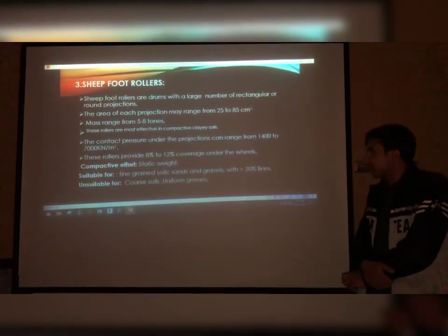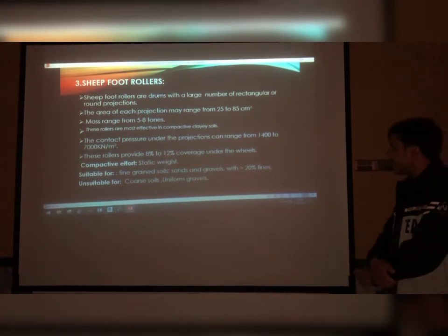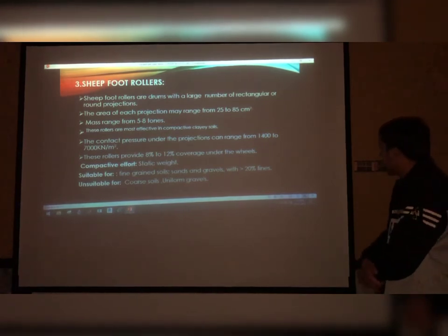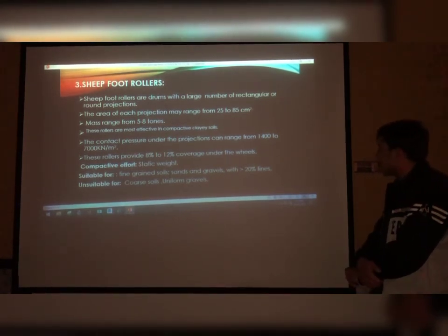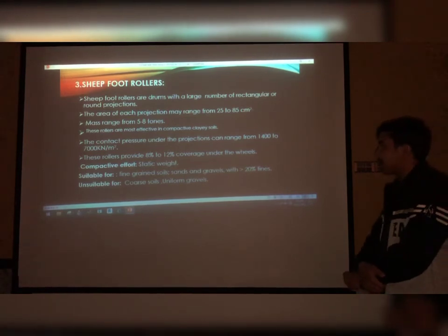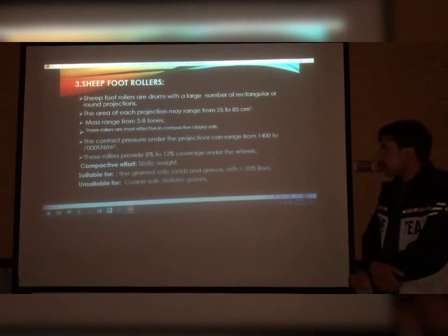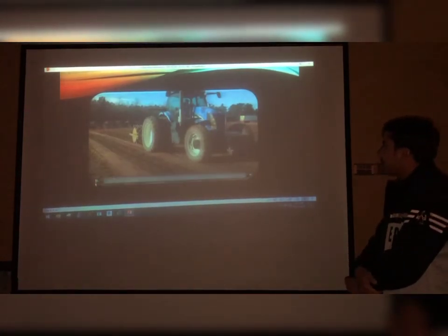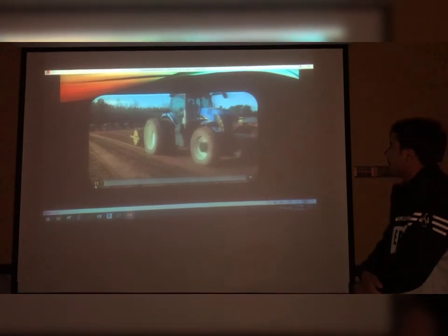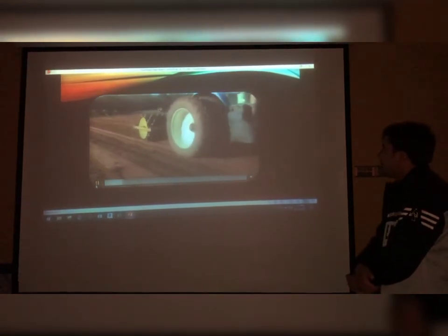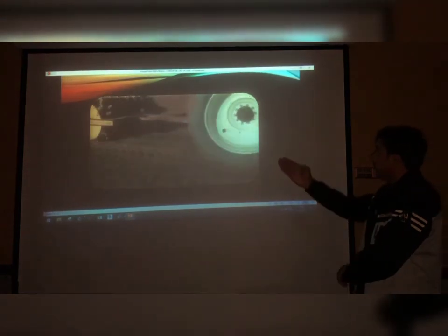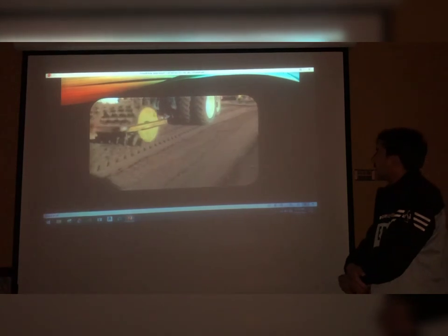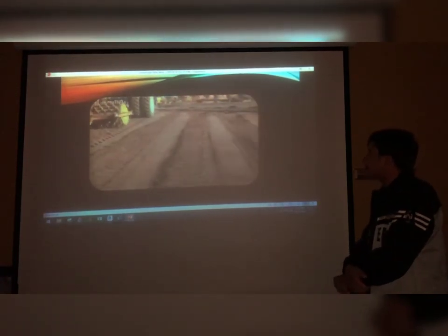Compactive effect is basically static. Suitable for fine grain soils, and for sand and gravel having a percentage of fines greater than 20. It is unsuitable for poorly graded soils and uniform gravels. You see here, these are the feet, the projections, rectangular or round. They can compact the soil.